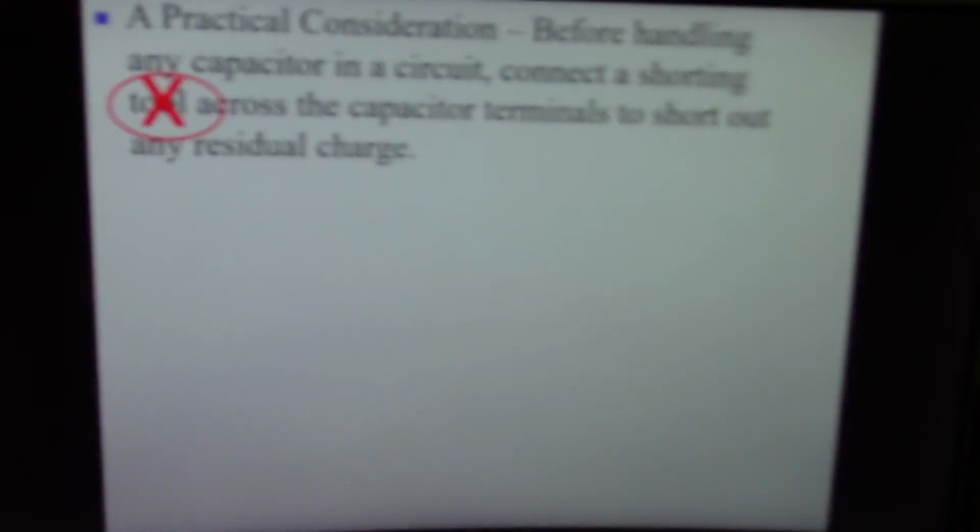You want to discharge the capacitor. The easiest way to do that is putting like a 1 mega ohm resistor, pretty hefty, a couple of watt resistor. Again, it depends on the voltage and the current of the capacitor. But a big heavy-duty resistor, when I say big, I mean the resistance of it, so that you slowly discharge the capacitor. What I have usually done, if I'm working on a 12-volt system, is just put a 12-volt light bulb across it.